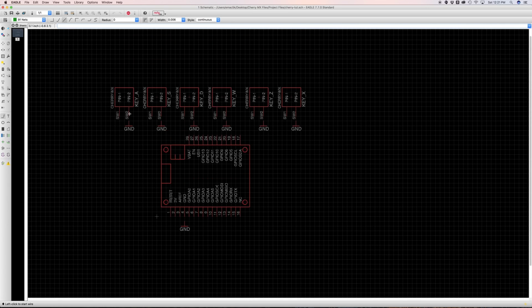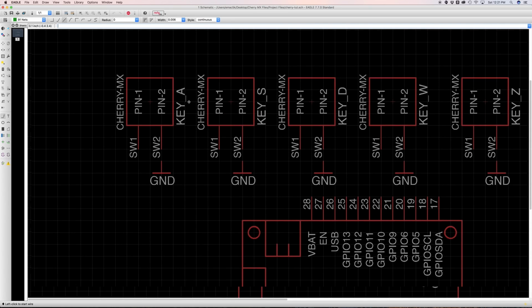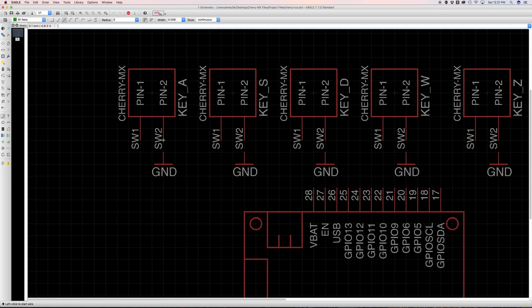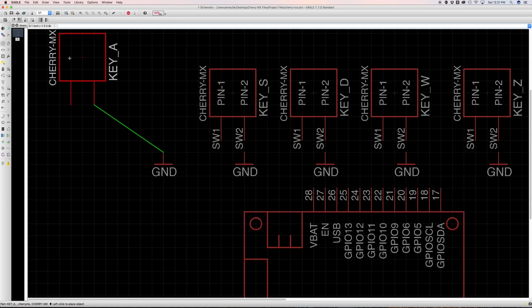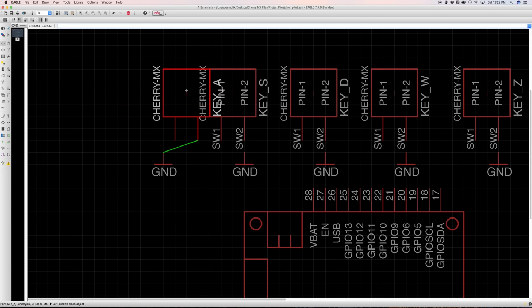To connect these, you actually need to do it tip to tip. So you see this little tip here of this line. I'm going to click on that, and then I will click again, but on the tip of the ground here, not over here or in here, but right there. Then I'll switch my tool to the move tool, and if I move this, you can see that the green wire is bending to wherever the position is. So this is telling me that there's a solid connection.